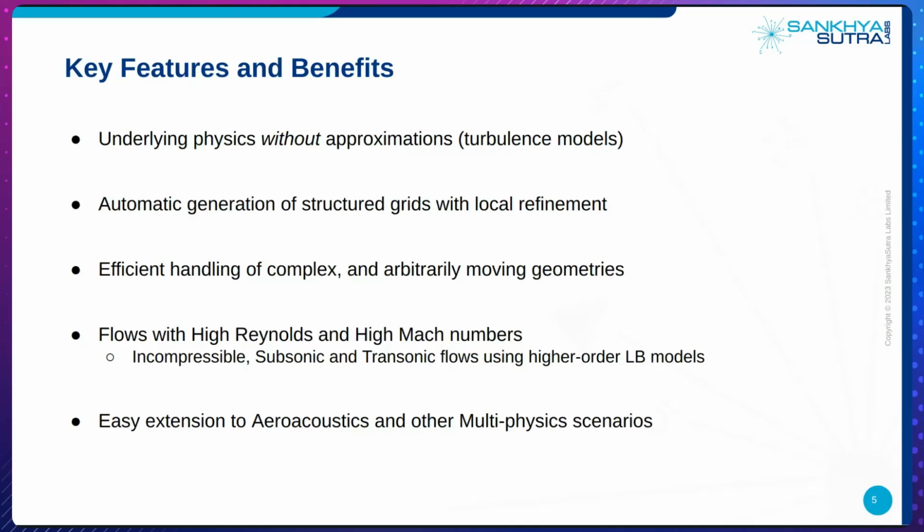We are also capable of efficiently handling complex geometries and also arbitrarily moving geometries such as turbine blades, propellers, etc. Since we also offer higher order Lattice-Boltzmann models, which are again models where we have a higher number of velocities in the discretized velocity space, we can also perform simulations up until the transonic flow region.